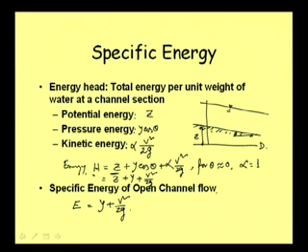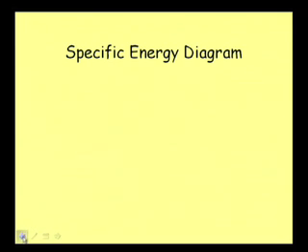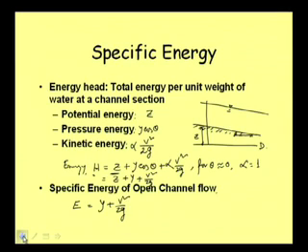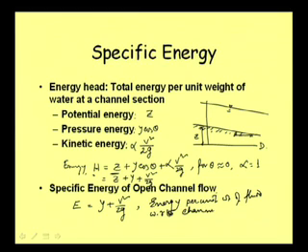That means, by definition, before going to the specific energy diagram, let me write the definition here, that is: energy per unit weight of fluid with respect to the channel bottom. That way we can write what we mean by specific energy.